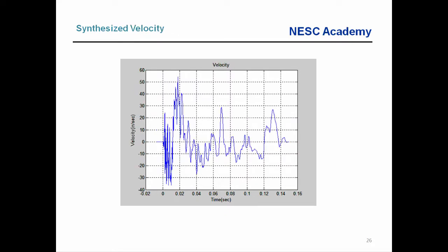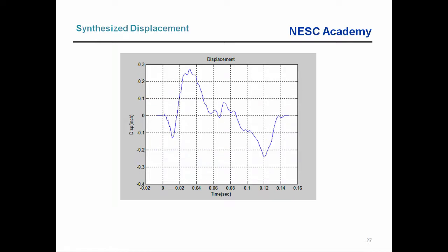And here's the corresponding velocity. The corresponding velocity is stable, and it ends at 0, with a bit of an oscillation about the 0 baseline. Displacements can sometimes be a bit one-sided. This one almost looks like an N wave, like for aerodynamic shock pressure, in other words, a sonic boom. That's just by coincidence. But this is a stable displacement. It's less than 3/10 of an inch, and it has a net value of 0. So that's a pretty good looking displacement time history there.